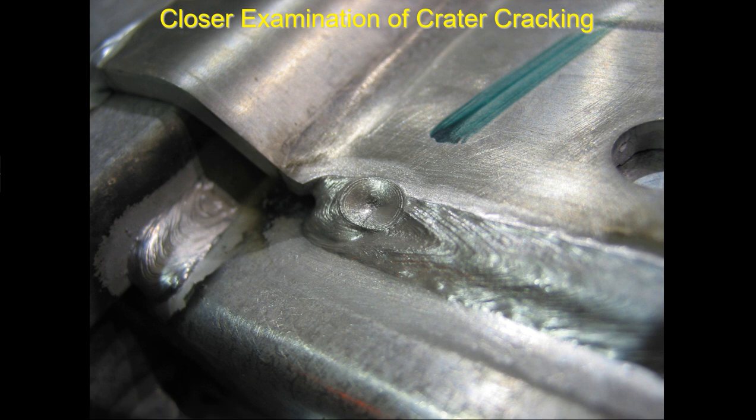It left it sitting here without fill, without any protection. It didn't have a chance to execute. So when it did, you can see that it left us a crack. Now this is a nice repairable crack. It does not extend out into the base metal. This one would require a little bit of die grinding.